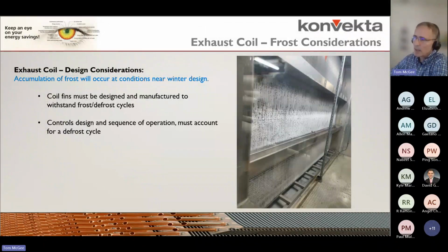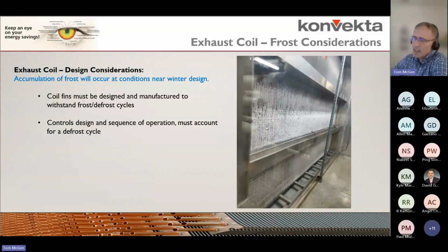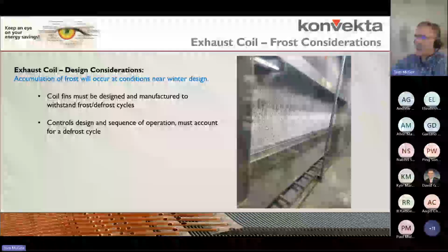So, as in the last example, we're not pumping the 20 degree fluid through the coil any longer. And what we found is the defrost process takes about 1/8 to 1/10 the time that it takes to frost it. So in our software, we establish the timing mechanism, and then we just start defrosting on a rotational basis.